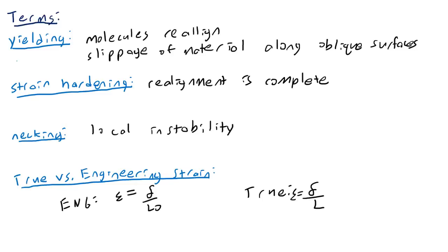However, the true scientific definition of strain would say that the L would actually be the completely unloaded, absolutely zero ideal length L, if this thing is completely unloaded at all. However, that is nearly impossible to create. Sometimes there is initial deformation or initial stress in a material just from its own manufacture.